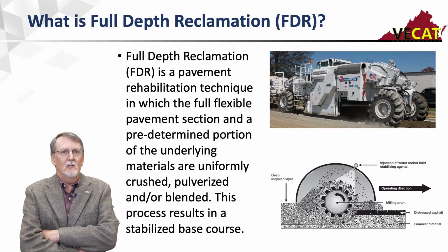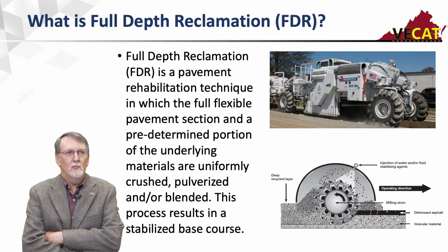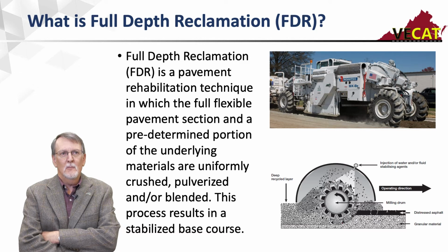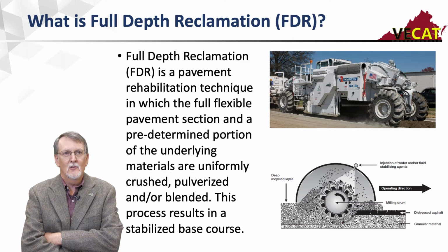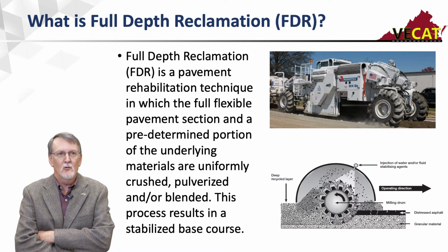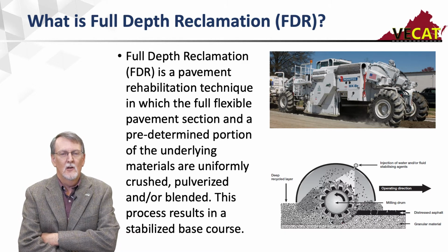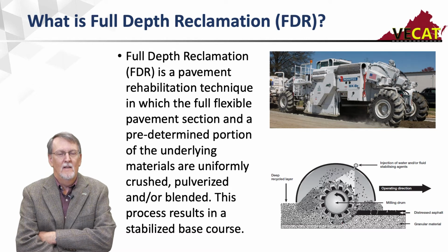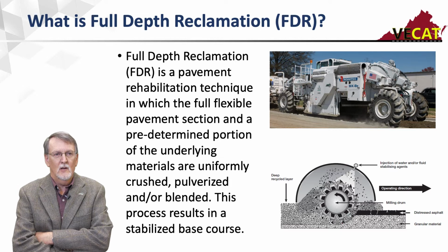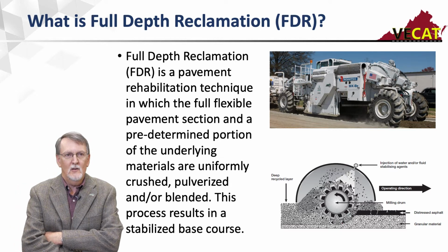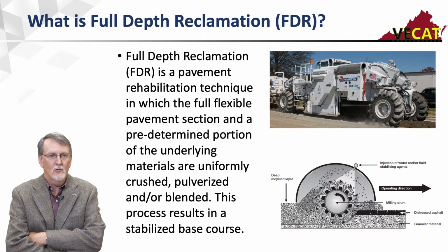So what is FDR? Well, full depth reclamation is a pavement rehabilitation technique in which the full flexible pavement section and a predetermined portion of the underlying materials are uniformly crushed, pulverized, and/or blended. And what we do is put it back down and compact it, and this results in a base course. And if we add a stabilizing agent, it's a stabilized base course.